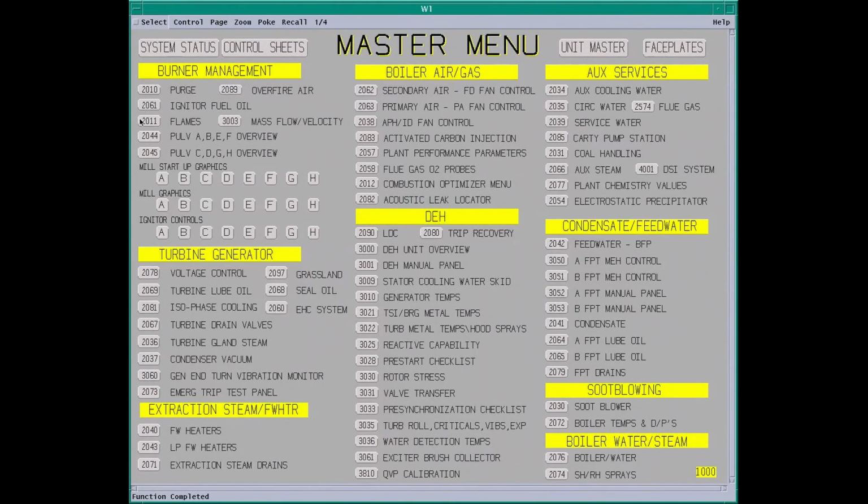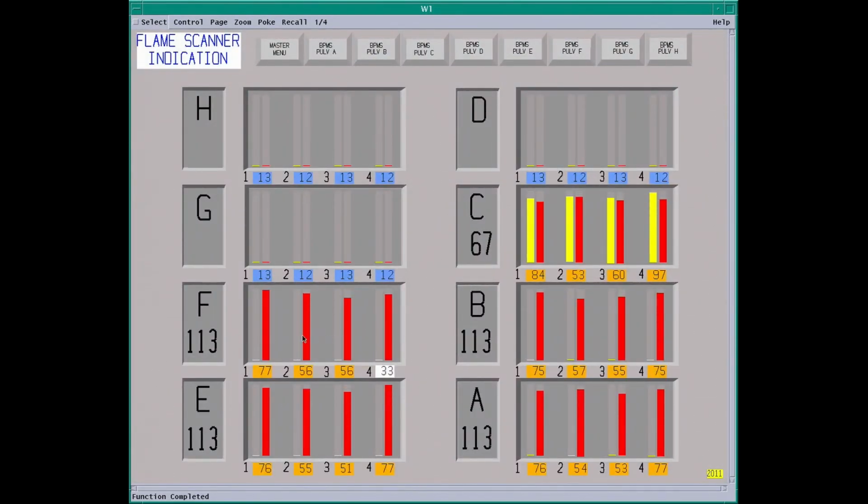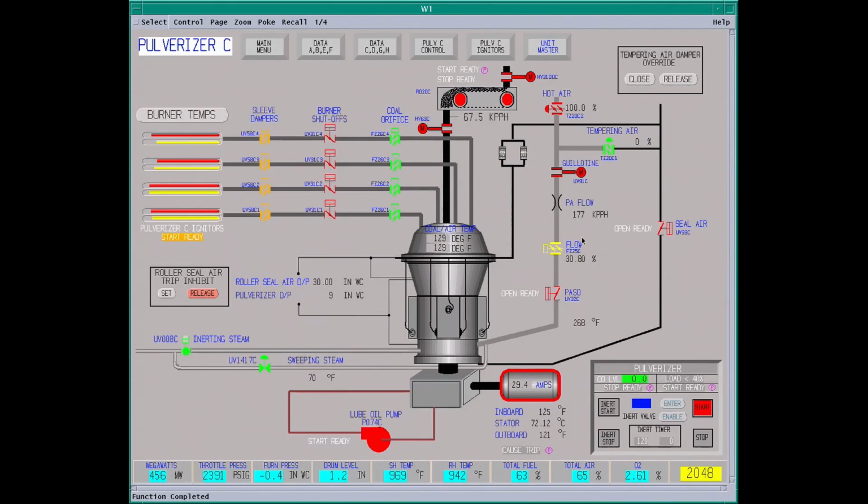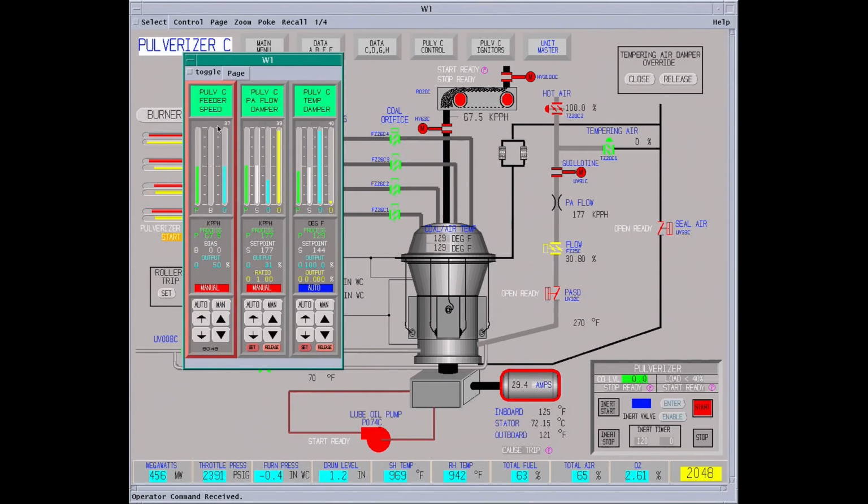Look at her. There's the flame screen. We've got 113,000 pounds on. Most of the burners are going to go to 134,000 before they load block. We got one sleeve damper down here that's failed, went closed. We want to get the igniters off as soon as we can. Kind of wasting some time here today, but burning about 15 gallons a minute of diesel.